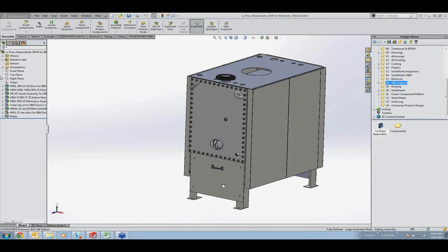I'll go ahead and float this sketch here, and then I can drag this back and forth. Not sure why that didn't rebuild. Sometimes if you suppress the linkage and then unsuppress it, it'll rebuild it. Not in this case.